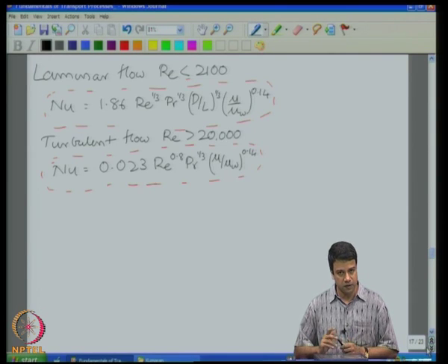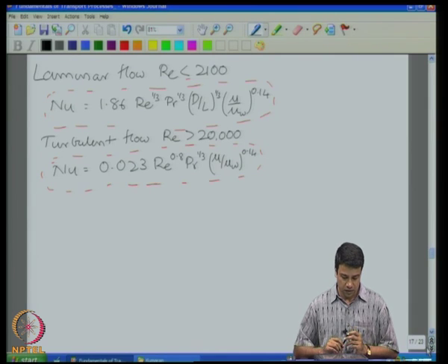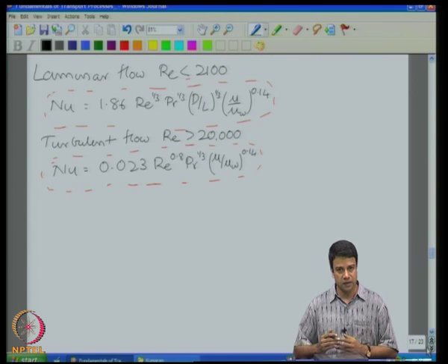If you want to go further, you have to do experimentation, change the Reynolds number, change the Prandtl number, and see how the Nusselt number changes or the average heat flux changes. And you get different correlations depending upon whether the flow is laminar or the flow is turbulent under different conditions. And you can actually have diagrams which plot the left hand side versus the right hand side.